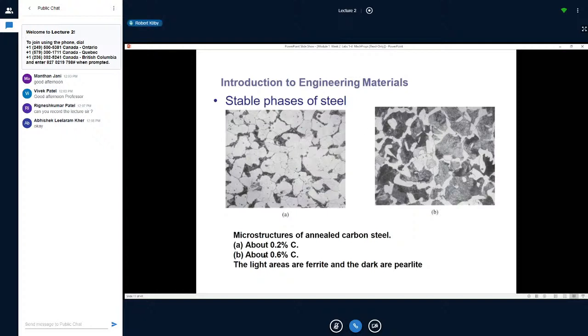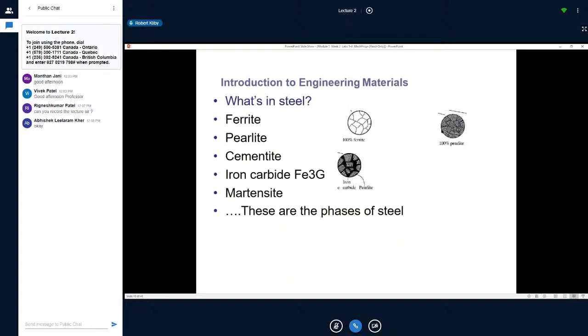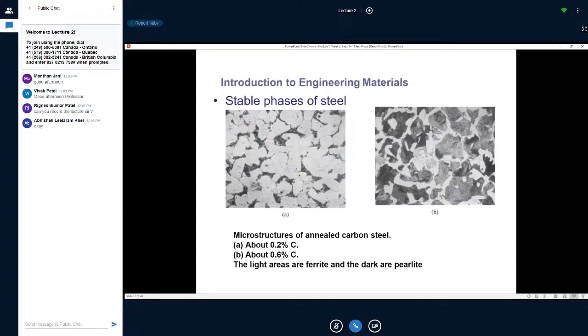This is another steel which has been produced at 0.6, so we're about 75% saturated, and the white areas that are left are parts of the crystal that don't have any of these lamellar fillings in. You can't see the straight lines here, it looks just literally like this with alternating white, which is ferrite, and then the carbon filling in between the lamellar bits.